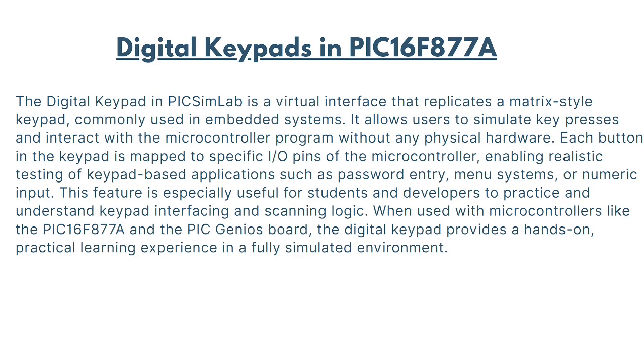Now we are going to discuss the digital keypads in PIC16F877A. The digital keypad in PICsimLab is the virtual interface that replicates a matrix-style keypad commonly used in embedded systems. It allows users to simulate key presses and interact with the microcontroller program without any physical hardware. Each button in the keypad is mapped to specific input-output pins of the microcontroller, enabling realistic testing of keypad-based applications such as passwords, menu systems, or numeric input.